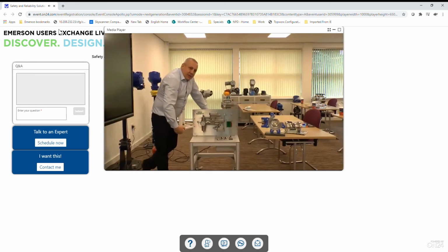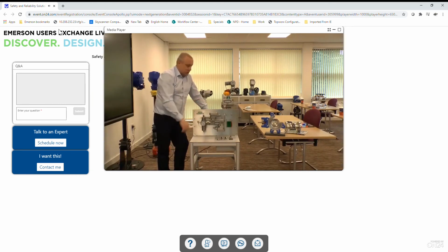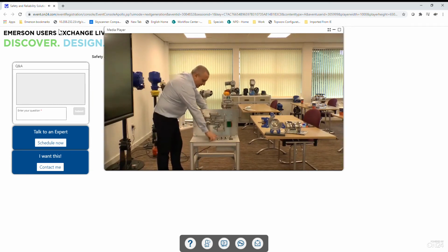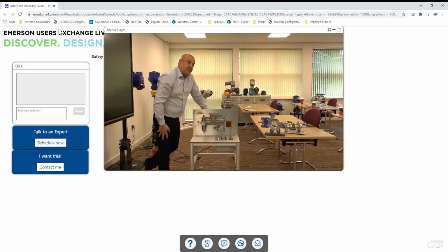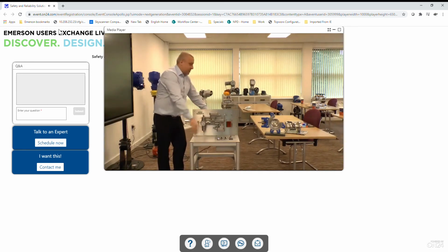The way this configuration is set up at the moment, the valves are in series. This is known as a 1 out of 2. A 1 out of 2 is more secure than a 1 out of 1 system, but is prone to what's known as spurious trips. I'll now initiate the valve. In this particular case, the valve in an actuated position is closed and the fail-safe position is open. Obviously that can be either way around depending upon the circuit. If it's an emergency shutdown valve, then the fail-safe position will be open or closed.